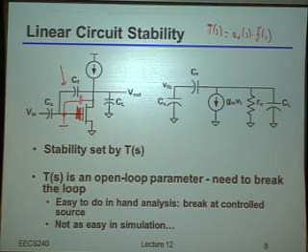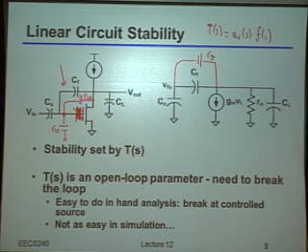Okay, so to be totally clear, when we broke this feedback loop analytically, if this was CGD and this was CGS, you would want to break it inside of that CGS and CGD. Because if you really did it the way I drew there, then our small signal model would have a CGD here, and an additional CGS there.